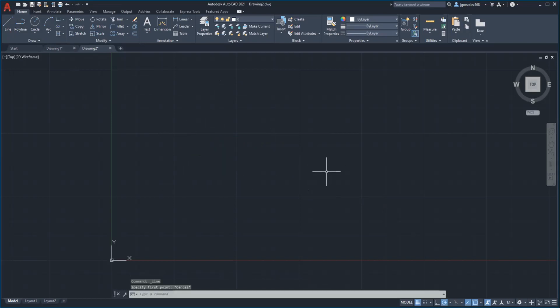Also, before we start, down here there's a snap mode. Go ahead and turn that on, the lower right toolbar here. So when you're drawing, it'll kind of snap to these little corners here, the units. And you can decide what these units are. Currently, they're 0.5 for every square. So 2 squares is considered 1 unit. And you can adjust that to be whatever you like. Or you can even change it to millimeters, centimeters, inches, which we'll do later. But for now, just make sure that the snap mode is on. So the cursor is right on there, right? You see that?